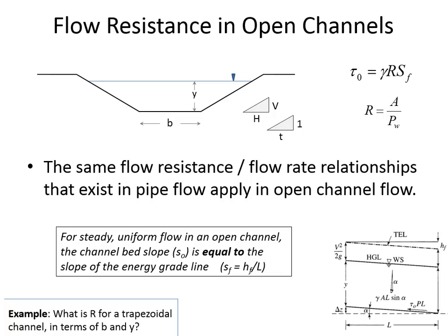You remember that video I showed you where they injected a dye at the bottom of a flow channel and the dye sort of just stayed at the bottom of the tank because there's no velocity at the bottom? We can look at that again when we get to it, but a velocity distribution would be very low velocities at the bottom, and it increases, and there'd be just a tiny little bit of a tapering there. So, I mean, there is some resistance, but it's minor enough that we don't include it in the hydraulic radius.